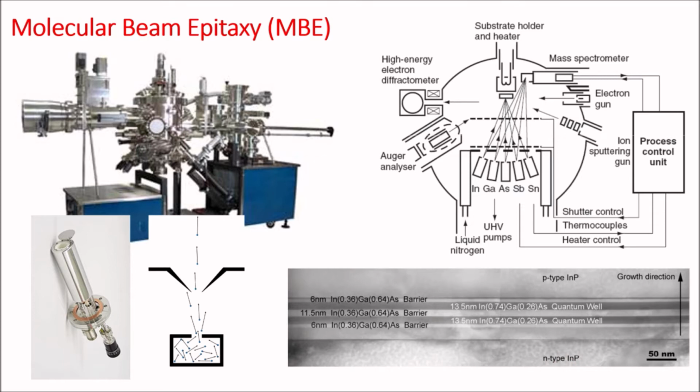Typical deposition rate is very slow and can be controlled to the order of 1 nanometer per minute. This helps us to have fine control over the thickness of the layer grown on the substrate. Hence, the MBE method is well suited for fabrication of quantum wells. An animation of the growth dynamics is uploaded in the Moodle, which you can watch to know how evaporated atoms are actually getting deposited on the substrate.